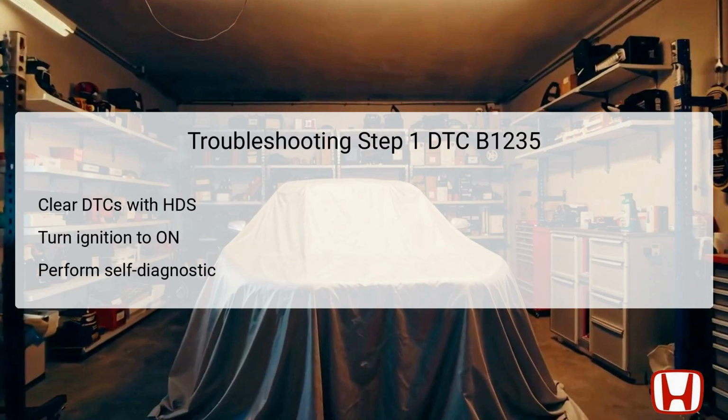The first step in troubleshooting DTC B1235 involves verifying the error. Begin by clearing the diagnostic trouble codes (DTCs) using the HDS, or Honda Diagnostic System. Following the reset, turn the ignition switch to the lock position and then back to the on position to prepare for the diagnostic check.